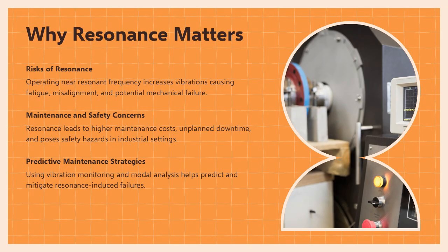Resonance poses significant engineering risks, making it vital to understand and control. Operating near a resonant frequency increases vibration amplitudes, which accelerates component fatigue, causes misalignment, loosens fasteners, damages bearings, and may result in catastrophic failure of mechanical systems. This slide emphasizes that resonance is not merely an academic concept but a critical real-world reliability concern.